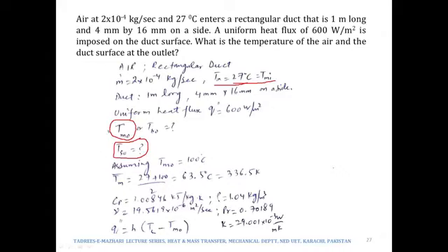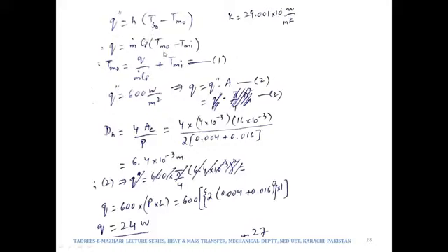So again, in order to find out Tm naught, we would be using the same expression. Right? It would be m Cp times (Tm naught minus Tmi). This is one expression, and if the parameters are known, we can also use this one, but we will see what data is provided to us.